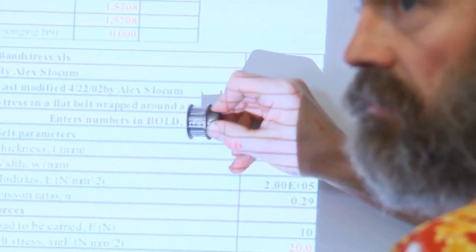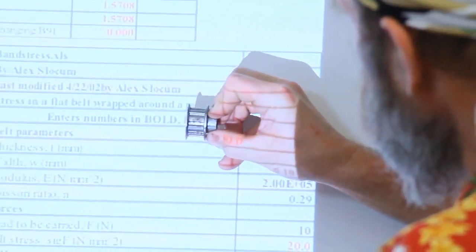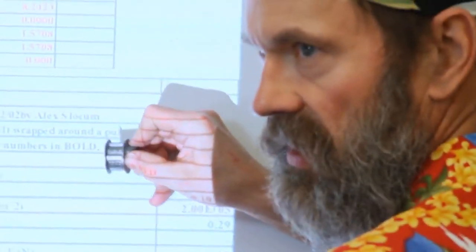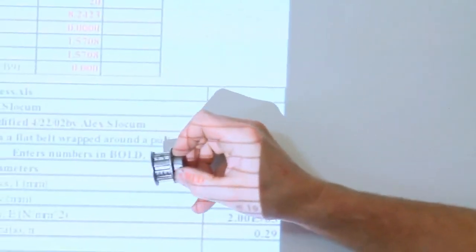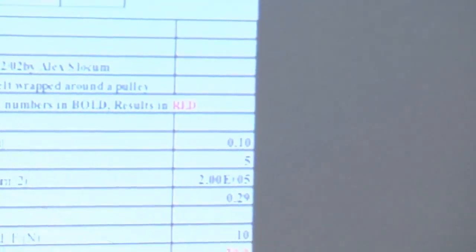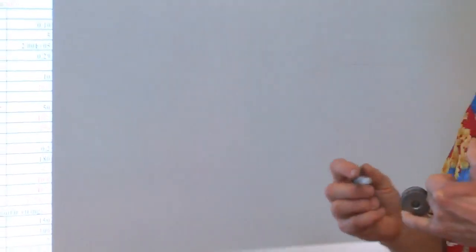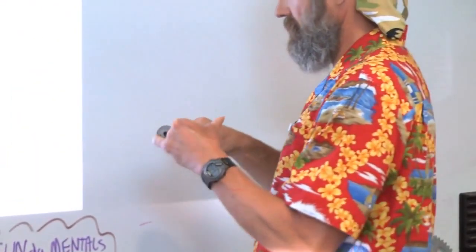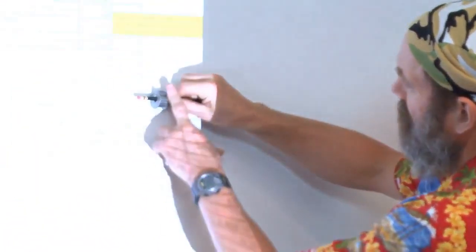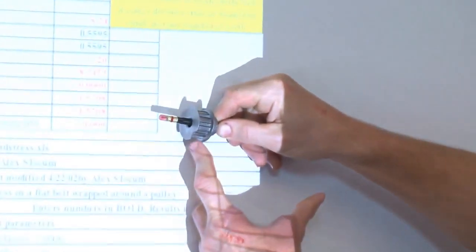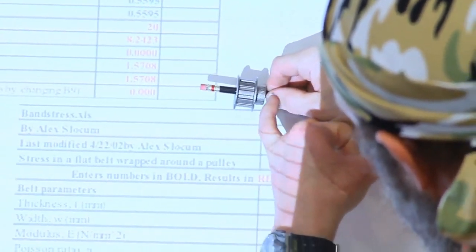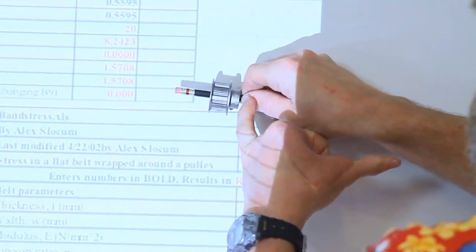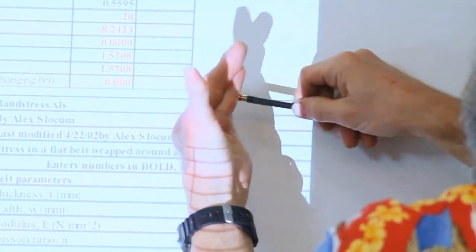And what else was I doing here wrong with respect to my emulating mounting a sheave on a torque source? Remember Saint-Venant's principle, and what we just talked about with how things are mounted and where forces are. The way I'm emulating there is I was making like I was the motor and I'm providing the torque to spin it. But look what is happening here. The distance between the center of the belt and the bearings and the motor that support it is a lot more than if I mounted it that way.